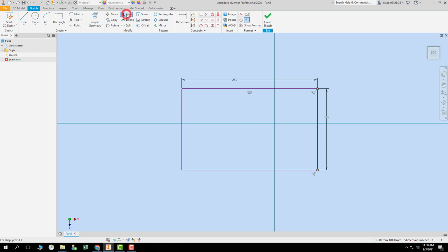Let's find out. Click on trim, click on the line. Ha ha ha. That's what it was. These yellow dots represent constraints, as well as these symbols like parallel. In fact, I believe I'm going to hit escape, get out of trim mode. When I hover on the yellow dots, it shows me the constraints buried within them, in addition to this parallel one.